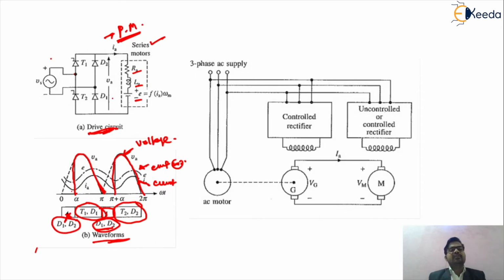Another very popular control method for driving cranes and hoists is called the Ward Leonard system, because, friends, we need speed control during acceleration as well as retardation. Most industries prefer the Ward Leonard type of drive for applications of cranes and hoists.